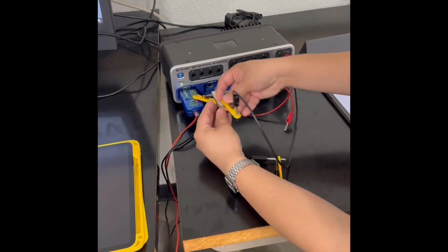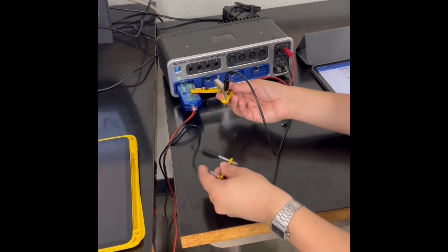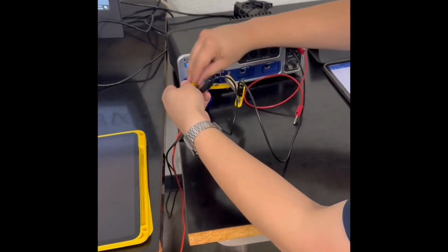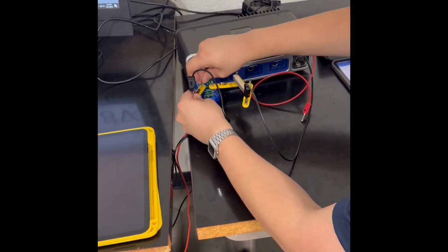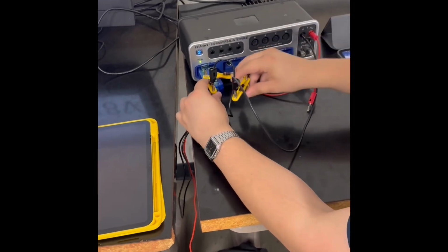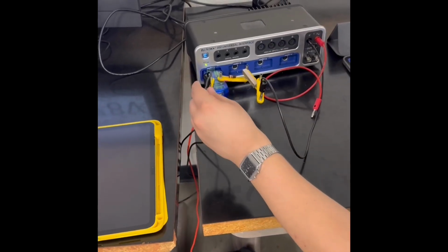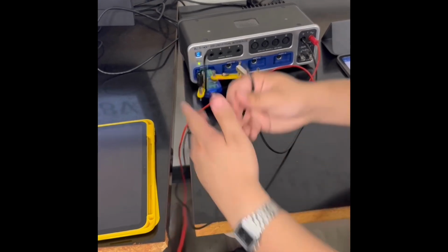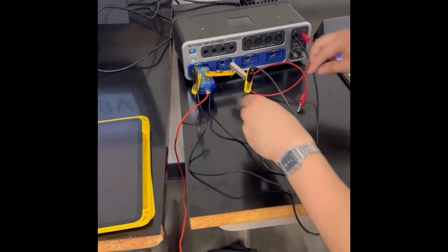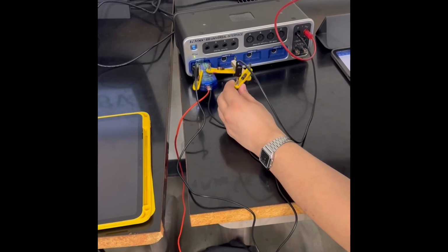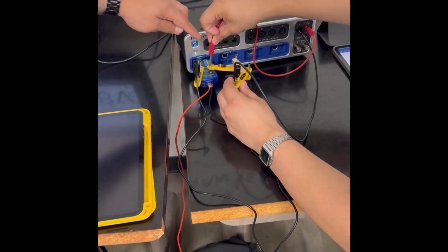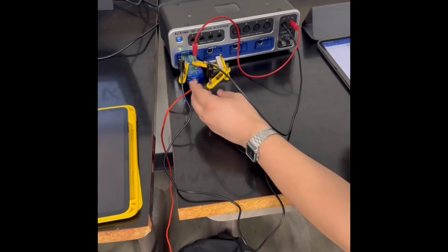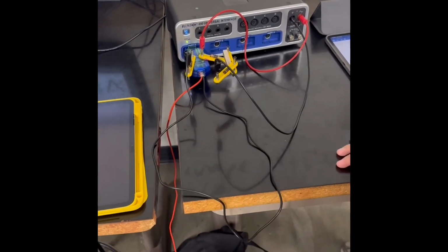Can you minimize these differences? Why or why not? While these differences can be reduced, it is nearly impossible for them to be completely eliminated due to physical limitations. One way to minimize them would be through using high-precision resistors with stricter tolerance ratings to improve accuracy. Further, ensuring that all connections are clean and secure will help reduce unwanted contact resistance. Calibration of measurement instruments before use can also prevent systematic errors, and maintaining a stable power supply allows the circuit to reach equilibrium before data is recorded.